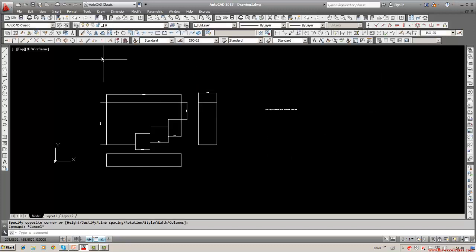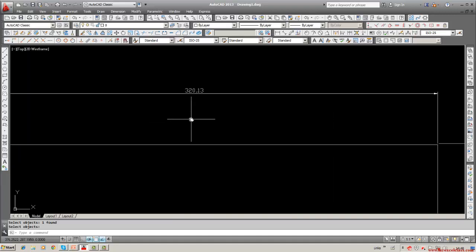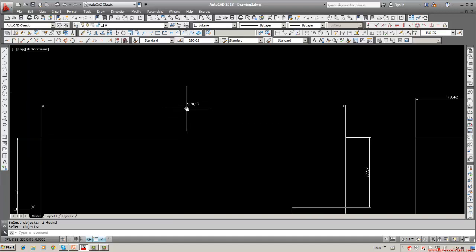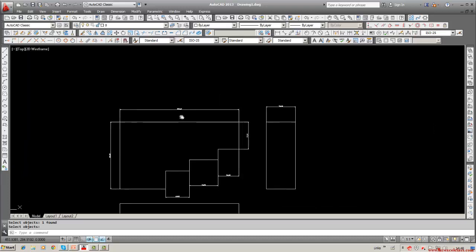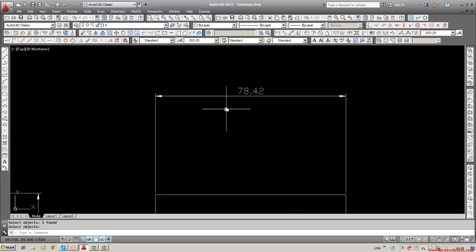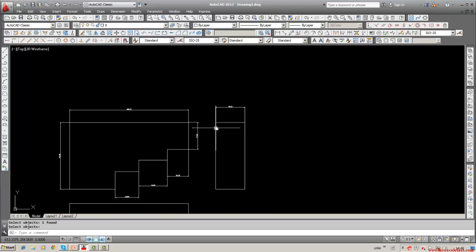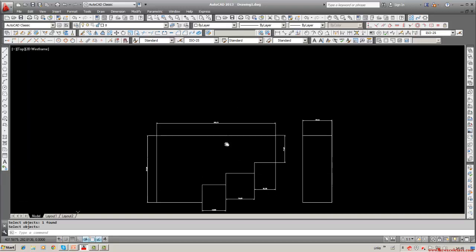So when we plot on a drawing sheet, the size will reduce. See, for example, we plot to scale 1:10. That is the actual size. On the drawing, 320 becomes 32, and similarly this becomes 7.8 if you draw it to 1:10. Then what is going to happen? The entire drawing is reduced to that size.